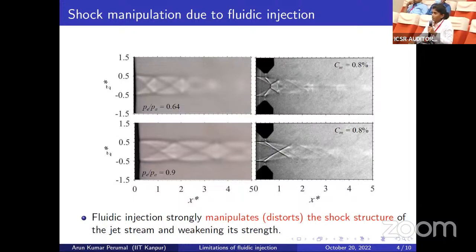Okay, but you mentioned that it weakens the strength. Yeah. But a regular reflection is becoming a Mach reflection only here, after the first shock. When we took the pressure data, the pressure magnitude was pretty low. So what I mean is that this particular change is somewhat significant over here, but when I move down to the first shock cells, it's completely weakened. Oh, okay.